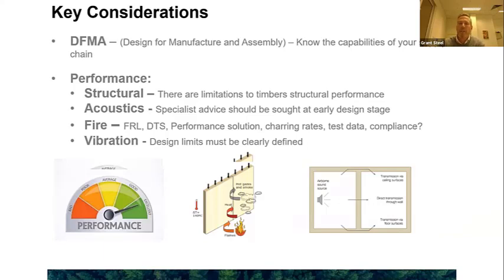So I think it's key for architects, engineers and the likes to design the mass timber elements with a knowledge of what the actual supply chain capabilities are. So it's important to know your supply chain. Classic example is a standard shipping container, I would say. Internal dimensions are limited to 2.3 meters wide, meaning that the maximum panel width can be no more than, say, 2.2, 2.5 meters wide. So the opposite of this is truck deliveries on a flatbed. These are less restricted and would enable the efficiencies of wide panel format and delivery, so more efficient installation.